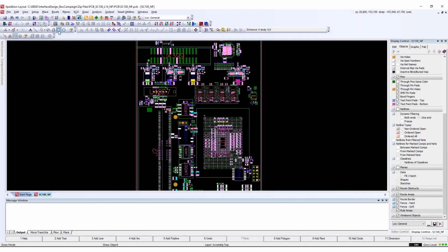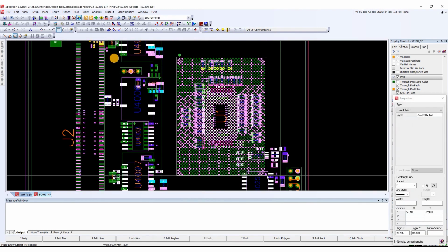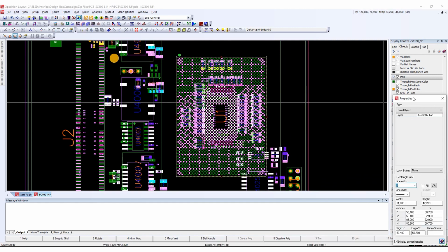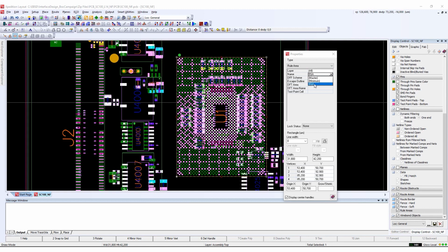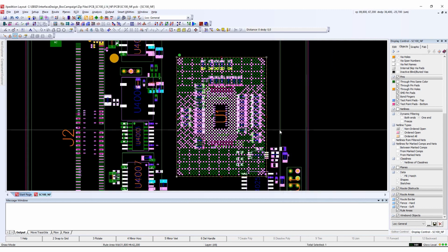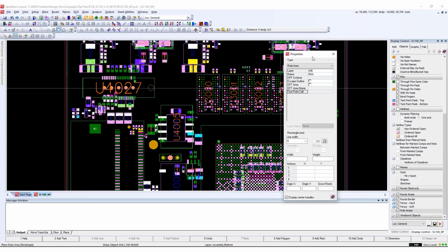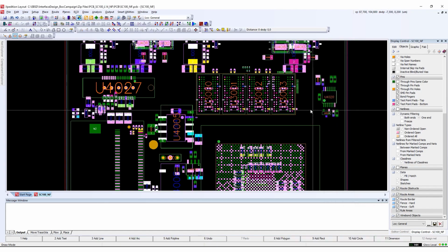Now that part placement is complete, Wilfred has exited the team session, and I will move on to drawing rule areas and relate them to rule schemes that the hardware engineer Kyle defined in the constraint manager. The rule areas will encompass the 4 DDR chips and the FPGA component to allow for different trace widths and spacing in these dense areas. Now that we have placed all the parts and rule areas, Wilfred can move on to FPGA optimization.